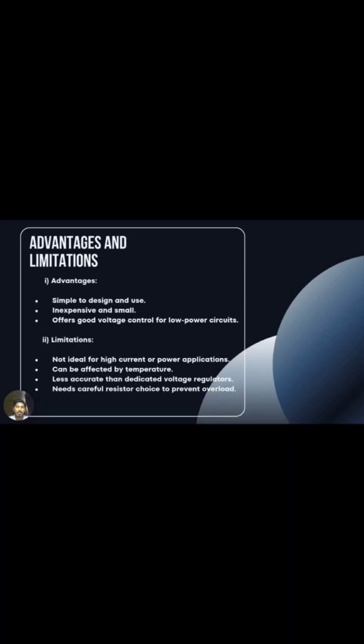The first limitation is that it is not ideal for high current or power applications. These methods are not efficient or reliable when powering loads that require large current. Second, it can be affected by temperature. The performance of diodes and resistors can vary with the temperature.